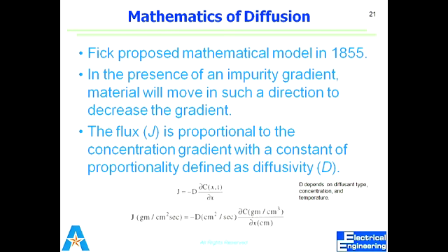This is one thing that people make a mistake on. When I say unlimited source, it means that when one atom diffuses in, another atom is replaced from the source. So you always have a constant concentration on the surface. Whenever two move in, you put in two. Whenever three are diffused in, three are added as well. So this is named pre-deposition. In pre-deposition, the surface concentration is constant.